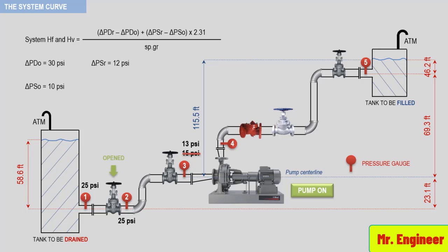Now we consider the pump. We have already discussed that the pump takes the energy that the suction gives to it. The pump adds more energy, jacking the energy up to the discharge pressure. In this case, the pump is designed with the best efficiency point of 94 feet, which also is the total dynamic head of the system.